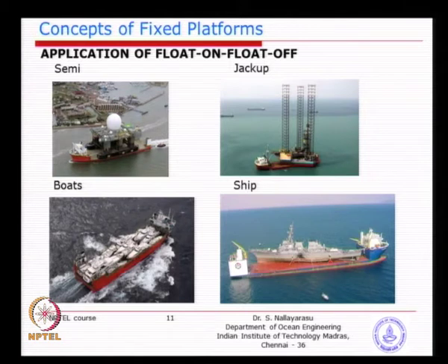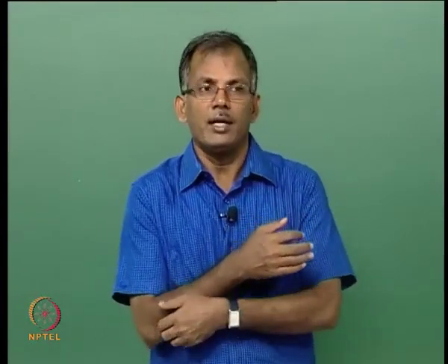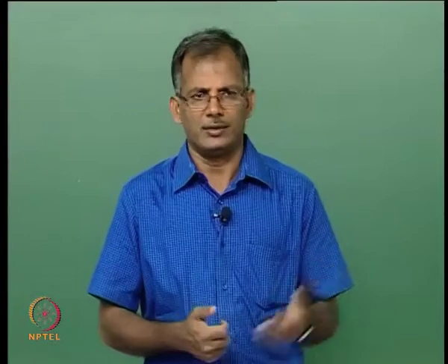A semi submersible can float and perform its functions at one particular location for oil and gas exploration, but it cannot travel a longer distance like a seagoing vessel. You must differentiate between a floating structure performing oil and gas production and a floating structure going for transportation like commercial vessels. They are two different classes, and you require different designs in fact. That is why, in most oil and gas applications, we have floating structures like semi submersibles.